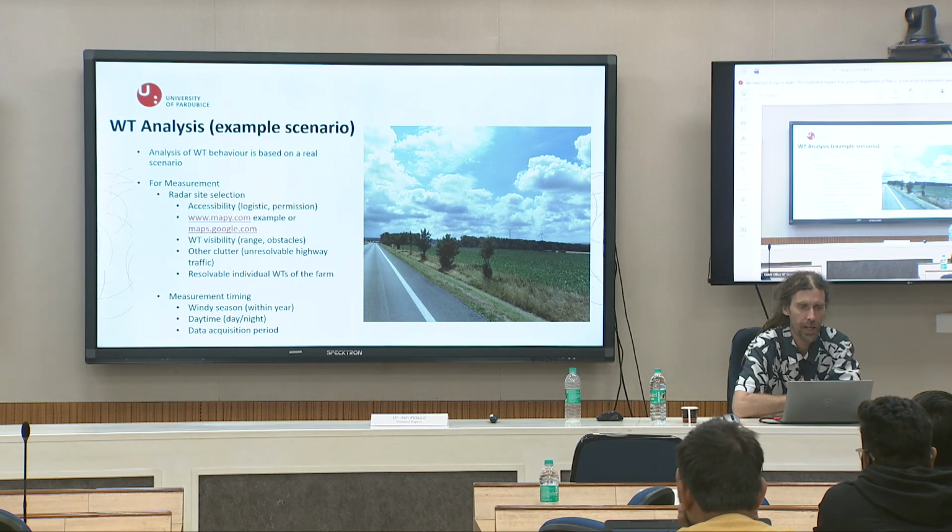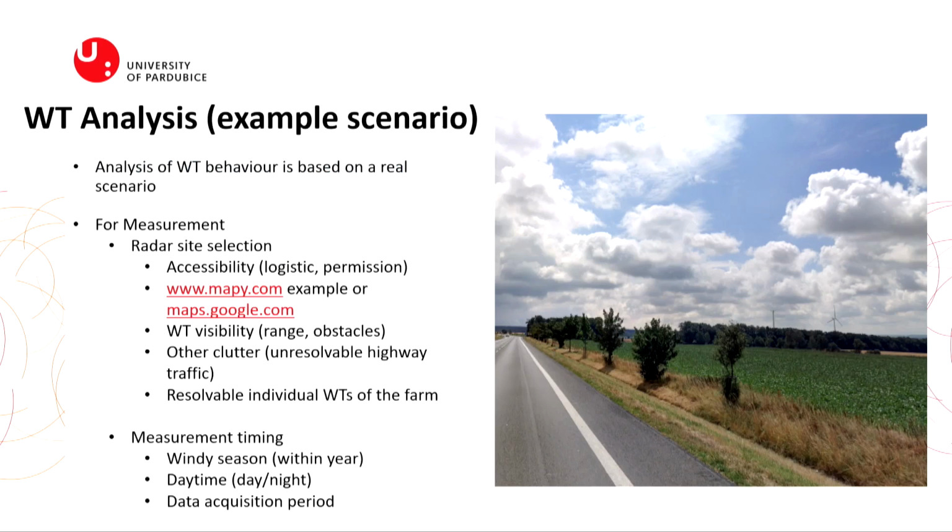And a very, very important factor is other clutter sources, and these could be highways, roads with high traffic, because wheels are a really great source of Doppler shifting effect due to their rotation. Trucks, everything could be a source of clutter. So for sure, before your measurement, you need to verify that there are no obstacles of this kind.